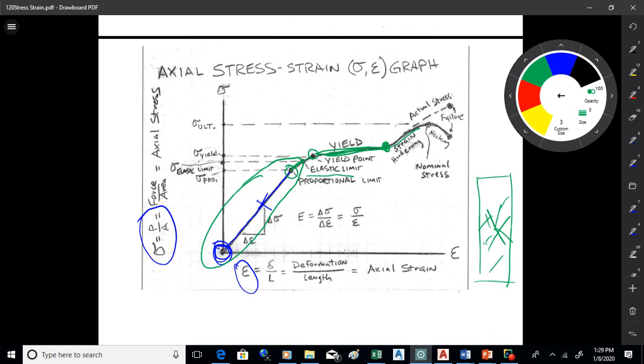So when all those fracture lines start to intersect and interfere, they harden up the material a bit. So you get a second rising section of the graph. And that will continue until you get failure. Okay. And the failure stress is called the ultimate stress.